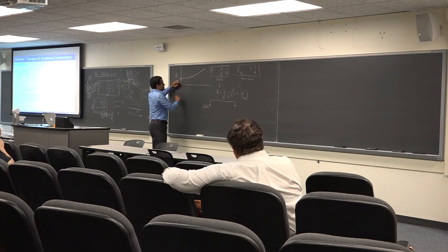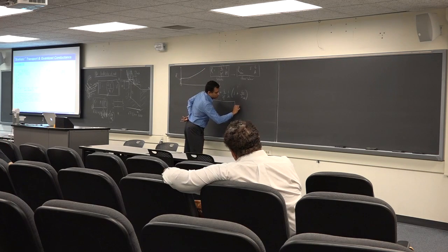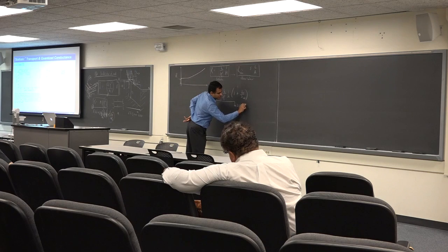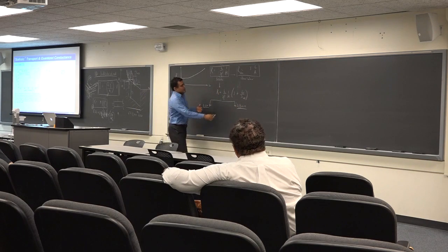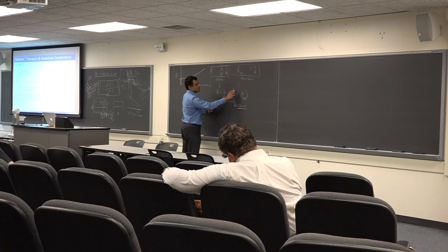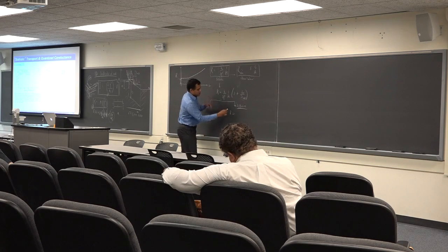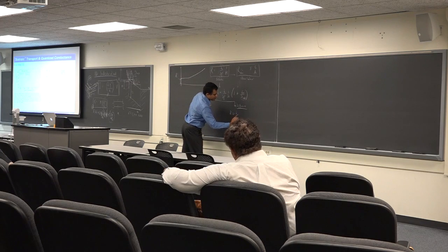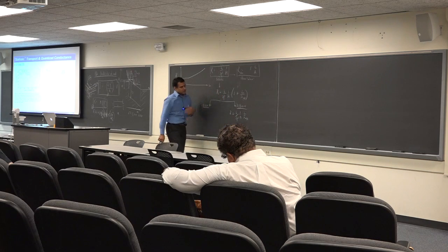Whereas in the long length limit, the diffusive limit, that's the Ohm's law term. In the diffusive limit, when you have a lot of scattering or a random walk sort of motion, the mean free path is very short. So this 1 is neglected, and your resistance therefore becomes close to h over 2q squared, 1 over M times L over lambda, the mean free path. So that's how it will look.